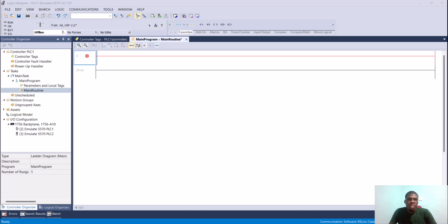Today we'll be looking at PLC to PLC communication using the message instruction of Allen Bradley PLCs. This is a way you can exchange data between two CompactLogix or ControlLogix PLCs using message instructions. In an earlier video, you can check my channel for videos on how to exchange data through produce and consume tags.